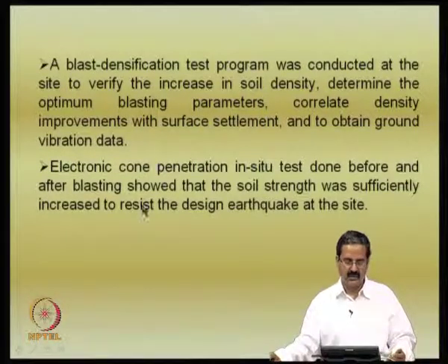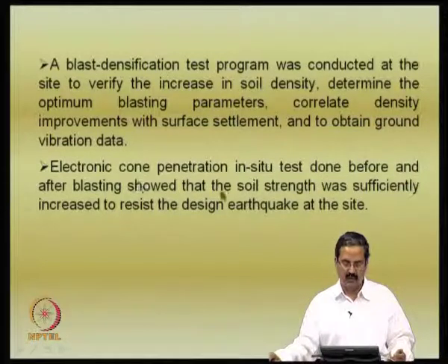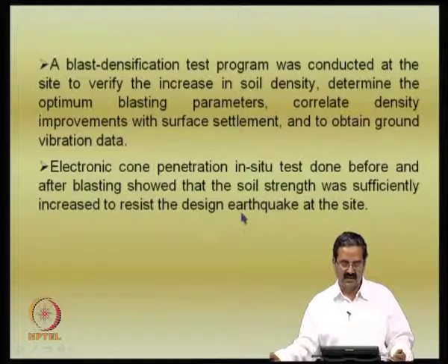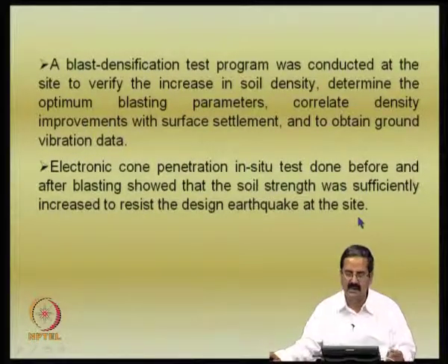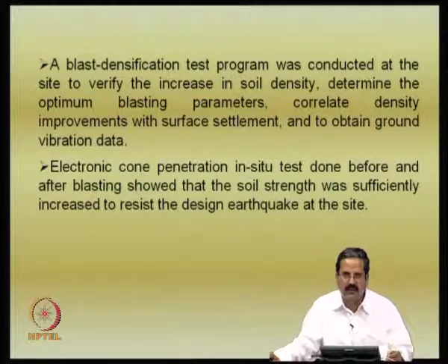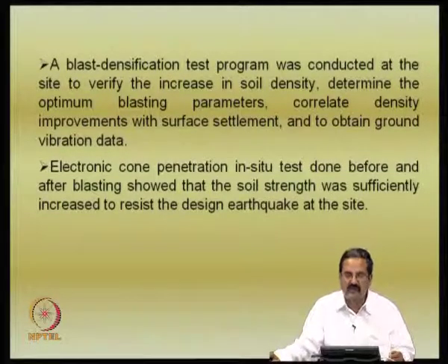They did a cone penetration test, in this case an electronic cone test, before and after, and the results showed that the soil strength had improved and increased to resist the design earthquake at the site. What was required was a very good ground improvement technique to match the design earthquake force.